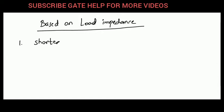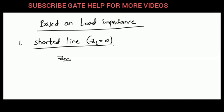Based on load impedance, the first type is the shorted line. For a shorted line, ZL must be equal to 0. Now if ZL is 0, then the input impedance of such a line is called ZSC, the short circuited line impedance, and this is nothing but Z of L, which we have already calculated for ZL equal to 0.